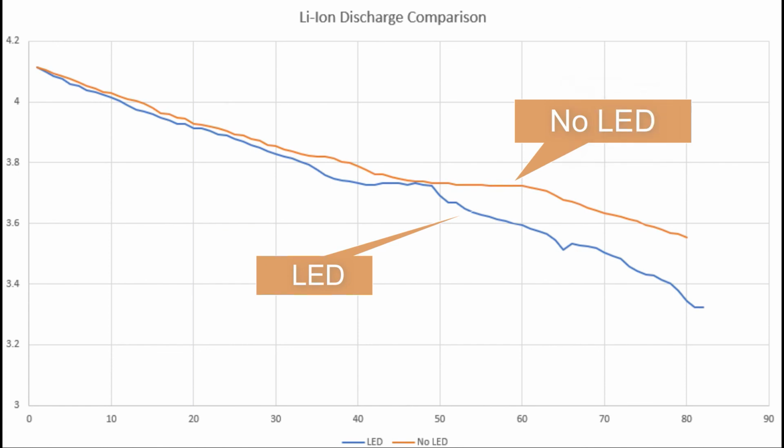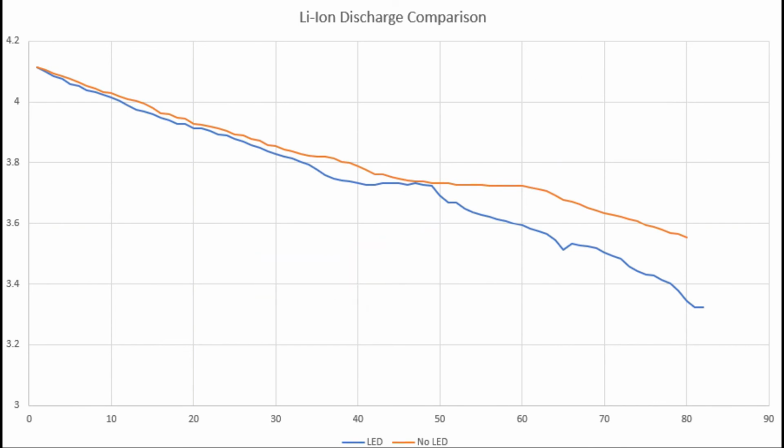Little difference in the discharge rate, but really not enough to make me want to keep going with not turning on the LEDs. So both cases it took about 80 hours or just over 3 days to discharge, which is more capacity than I really need anyway for a backup battery, when mostly the boat monitor will be running off the house battery.